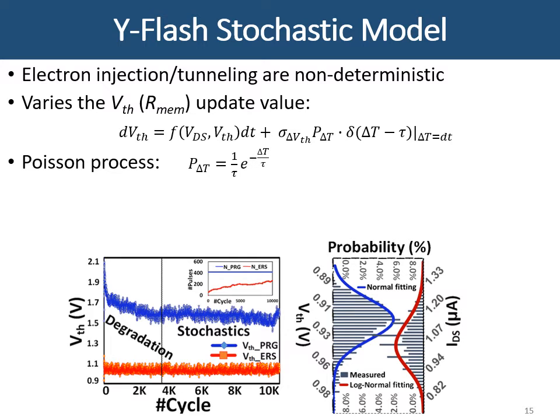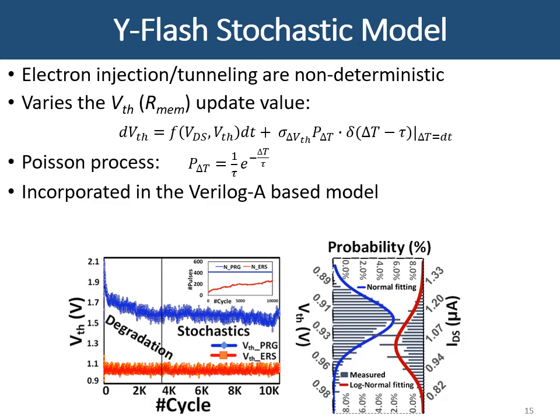We fitted the proposed model to the experimental measurements and characterized the statistical distribution of the state variable and currents in erasing and programming modes, respectively, as shown in the figure. This model is also incorporated in the Verilog-A-based SPICE model, and stochastic dynamics can be flexibly simulated to evaluate the overall effect on the performance.